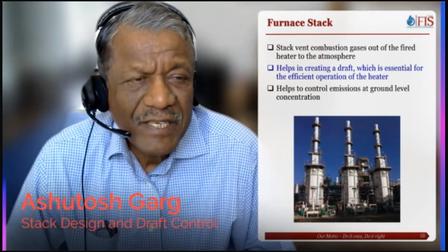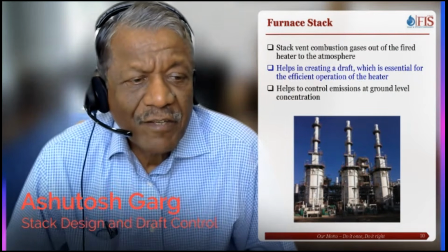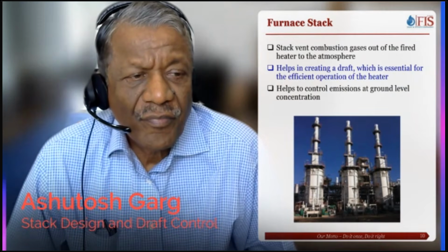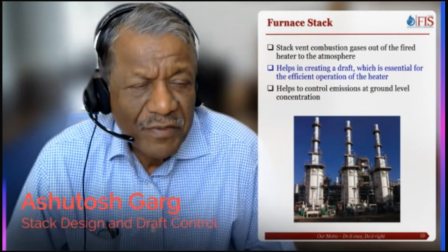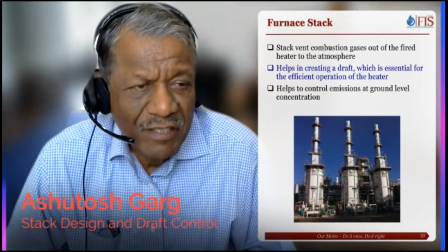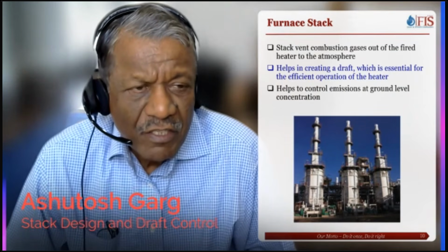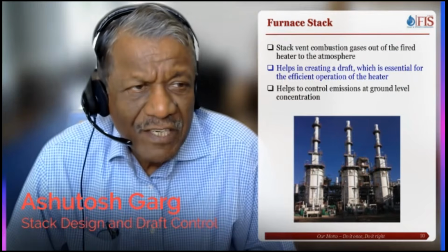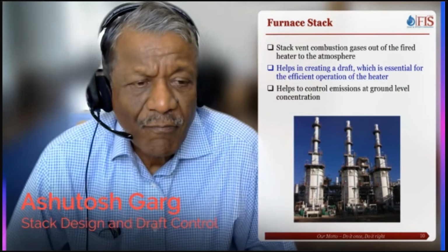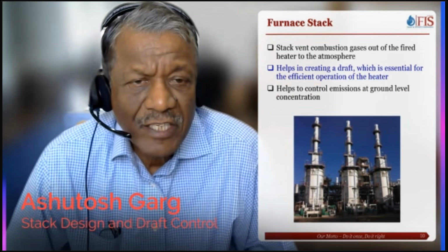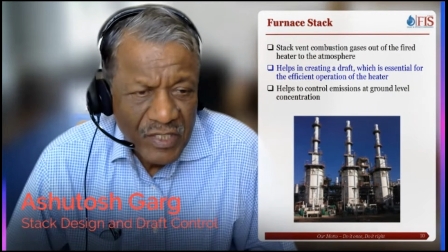So we keep negative pressure inside the firebox, inside the combustion chamber, inside the convection section, everywhere. So the main function of stacks is to create negative pressure in natural draft heaters.